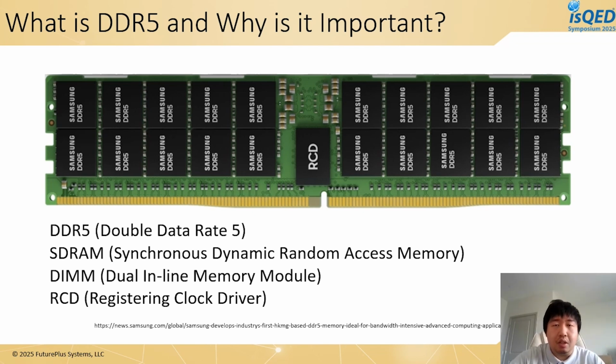And the DIMM usually has a lot of individual DRAM chips on it that form channels of memory. In DDR5's case, each DIMM will have two channels on it. Each channel of a memory has an independent data bus connected to the memory controller of a processor. There could be what's called a rank on a DIMM, which are extra DRAMs that share the data bus of a channel of DDR5, which expands the capacity of a DDR5 RDIMM or regular DIMM.